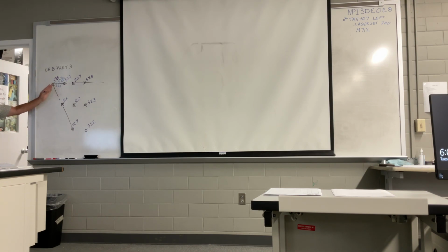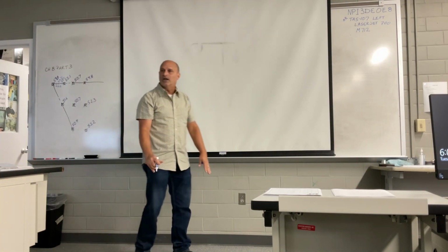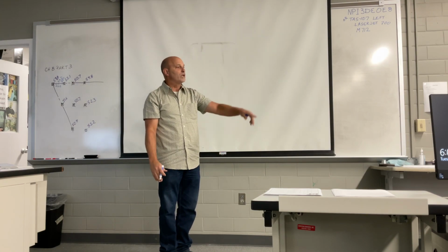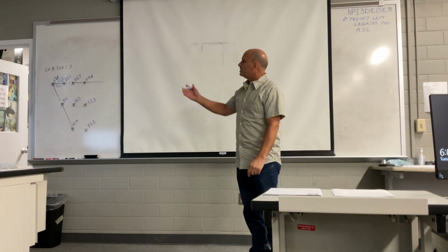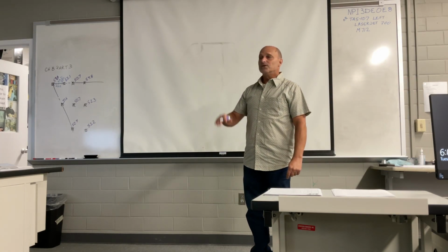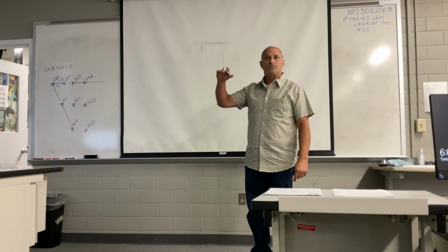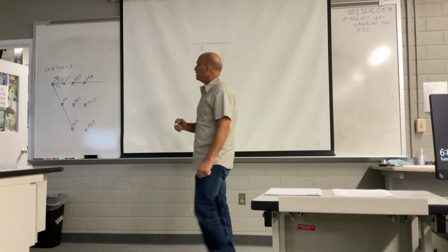There is no set spacing. We're not out there measuring. We don't have anything that tells us from this point, it goes 3 feet to that first interval change, another 6 feet, we don't have that information. We just know that between these two points, it goes from 52.1 elevation, so maybe we're out there and it's ground level right here. And as we're walking to that next point, it's steadily getting higher and higher until we get to that other point, which is 53.8 elevation. So remember, elevation is just a height above something. In this case, normally it would be above sea level.